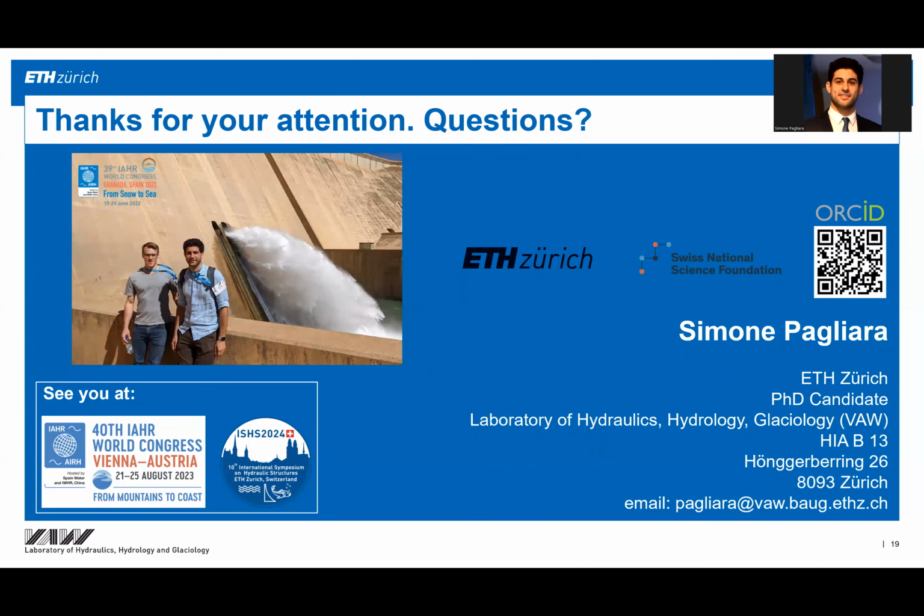I completely agree with what you're saying, but I think that's actually a limitation of physical modeling that we cannot overcome. The bubbles in your physical models will always be about the same size as in the prototype, so they will not be geometrically scaled, except by changing the fluid, which is not something that we can do, of course. I see it as one of the main limitations.